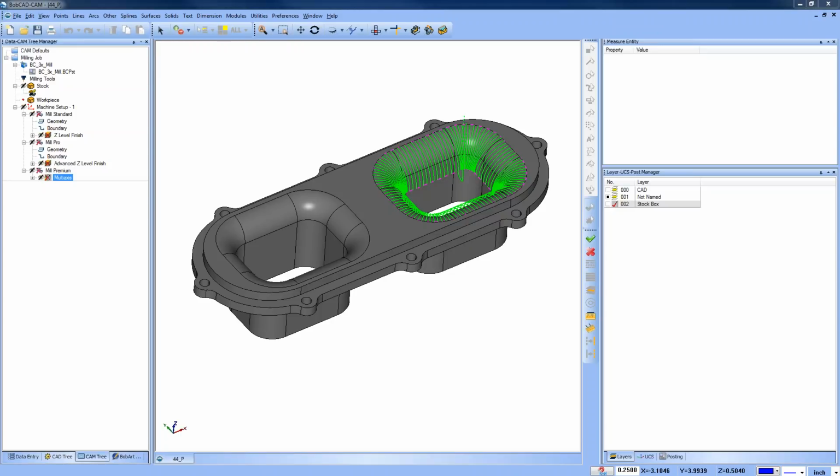I know I am. Brian had a question, best step over based on the tool diameter. That's another really good question. Your cusp height calculation and what step overs you should be using, or what size tools you should be using. These are things that have to do with your equipment, your part, your experience, your software, all together. Okay?